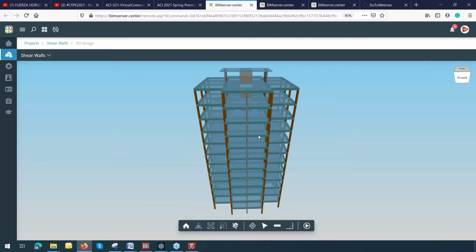Now from the shear walls program, we create a new project. We give the name we want, anything you want. If we just say yes, for example, to import the BIM model, because it's always a BIM model, and once this part is done, we can select the project, show the drawing, because they're going to show you some kind of drawings. Then you can detect the shear walls and the couple beam. There are certain requirements once you start working with the program